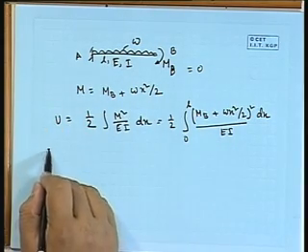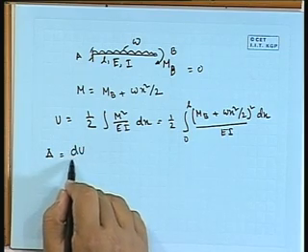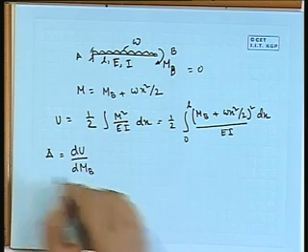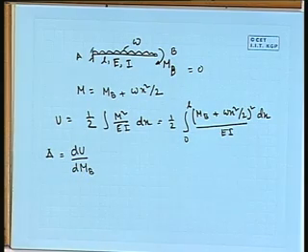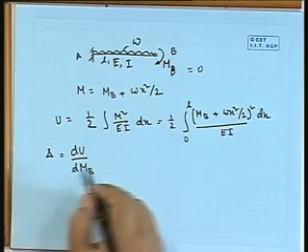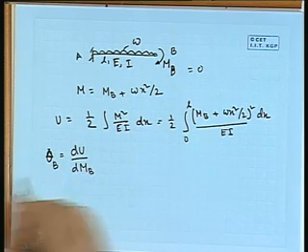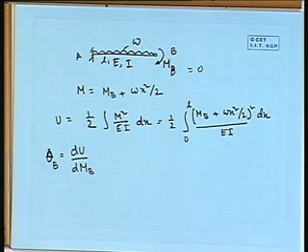Now, if we calculate delta, it is basically du by, here it will be MB. Okay. So, we are interested for finding out the slope at B. Corresponding to slope, we are supposed to give some moment M. So, it is at B, MB. So, this delta here is nothing but, we can rather write theta B. So, theta B will be du by dMB.